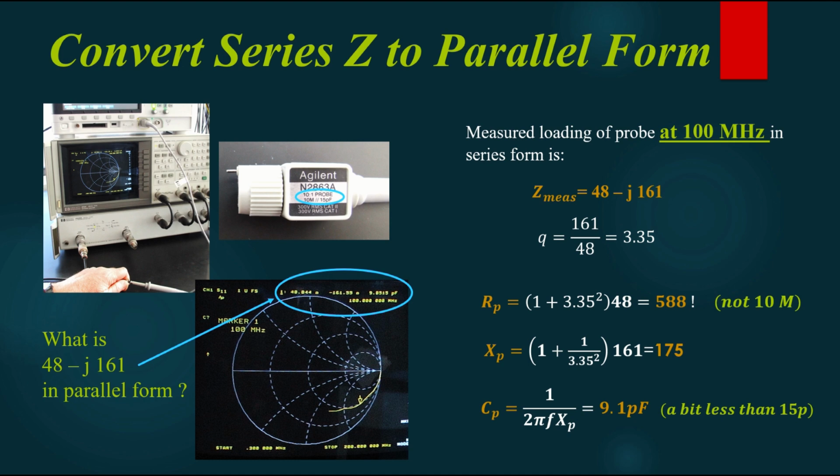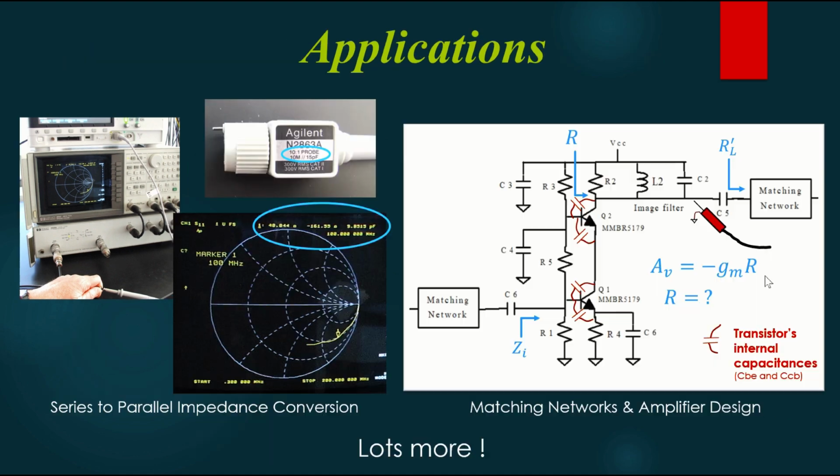and that's how I found this. I was measuring some circuits. I went, what's going on? Well, this is what's going on. So just remember this if you try to use an oscilloscope probe, even for a very high frequency. If it's a passive probe, then the oscilloscope probe can really load your circuit.